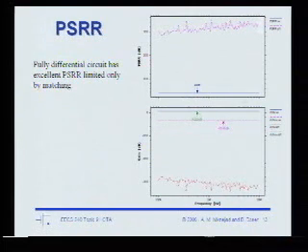Well, there's probably some capacitance, right, between VDD and the output. And so you're getting a signal feed through directly to the output. If that were the case, then this would go up with frequency, right? But it's flat with frequency. So what's causing it?